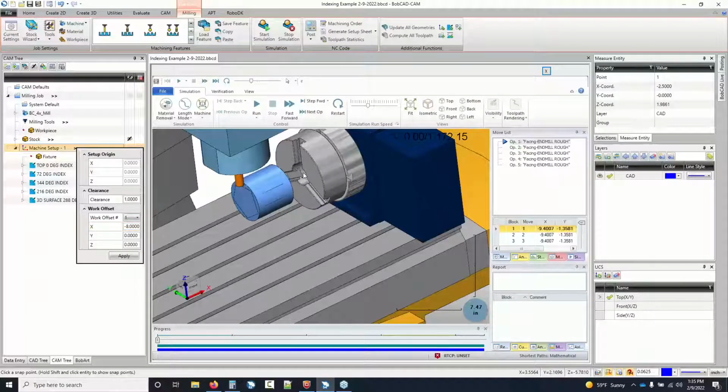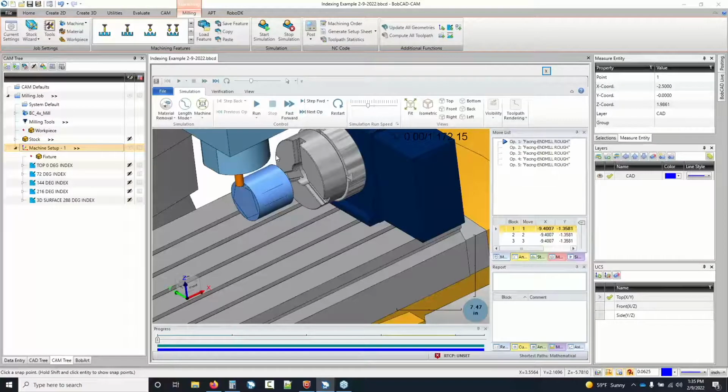That's to go from the front face of this rotary out to right there. That brings us 8 inches out on that part. Again, you might need to go more, you might have to go less, but really you should be accounting for the length of your part, the length of any extra stock, as well as the jaws. You might have a little extra for the jaws.